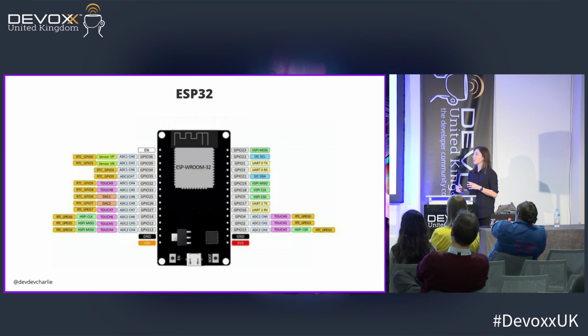Also, some of the pins on the board already have touch sensitivity, so you can track capacitance, it's capacitive touch, without having to write your own program. Using the ESP32, they have a function called touchRead that gives you the amount of capacitance without you having to write anything more. So yeah, that was a main change that really helped me.